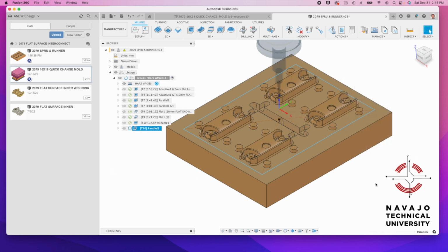And this one is probably going to take 5-8 hours or something like that to run. And it's a very fine step that it creates, and we can pretty much pull the mold out and stick it in the molding machine and start making parts. So a lot of guys will sample a mold, and then they'll measure parts, and then they'll hand polish it after they've sampled it. But a lot of these modern machines that run at these high RPM spindles can deliver some extraordinary finishes.